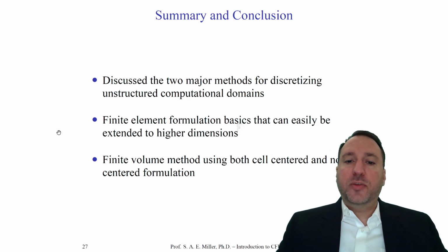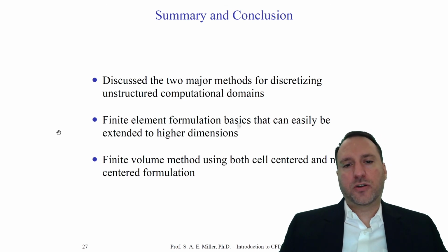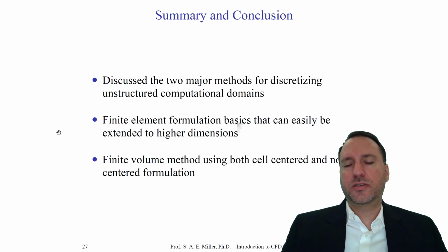Unfortunately, the finite volume method itself, as you see, is almost always restricted to very low order. For example, first or second order at the highest. And so a finite volume method might be simple, straightforward, physical, and not produce the so-called weak solution like the Galerkin or finite element approaches, but it's restricted to low order. That means to find the equivalent accuracy solution as a finite element approach, many, many, many more volumes in a finite volume solver would have to be used. This is a disadvantage of the finite volume approach.